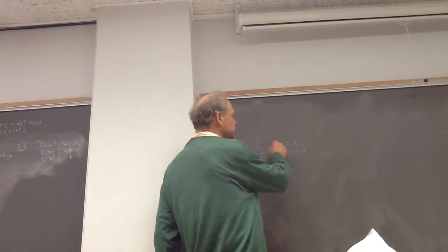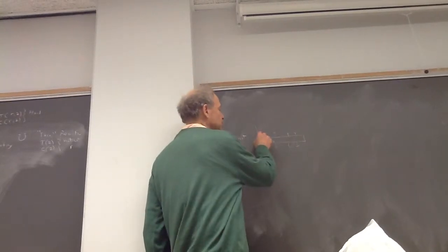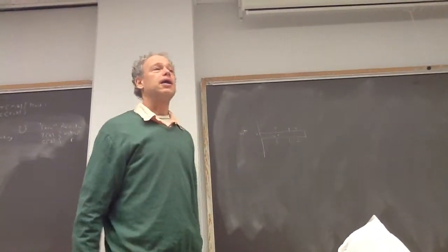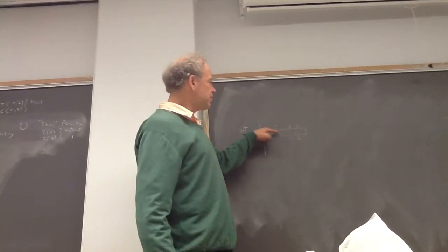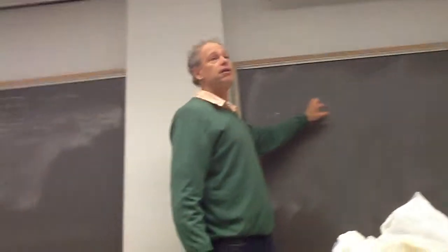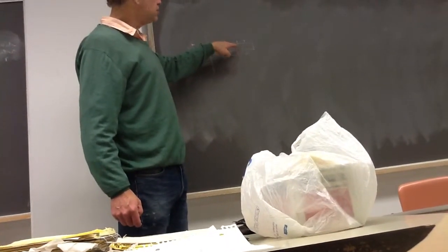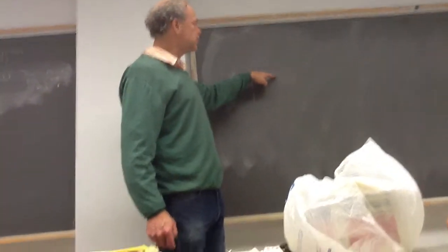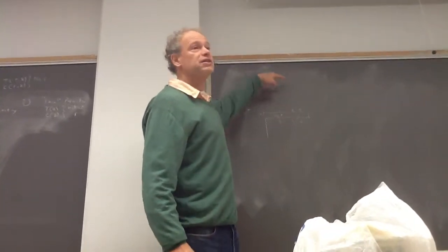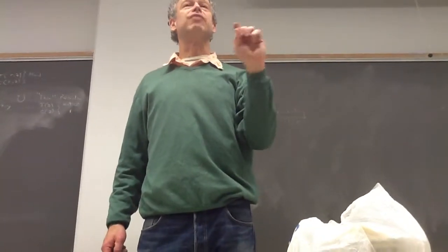Then typically you solve the heat transfer problem in this region, and you've got two directions, X and Y. In principle, the temperature should be a function of X and of Y in this case. But if the fin is thin, well, what does thin mean? Basically it means that the conduction in this direction is fast compared with the heat transfer of the Newton cooling. So thin isn't an absolute thing, it's a relative thing.